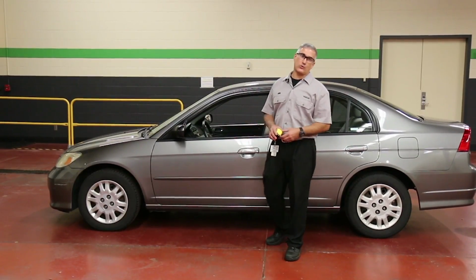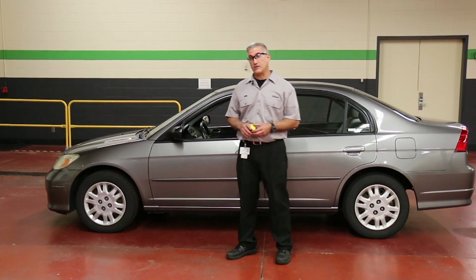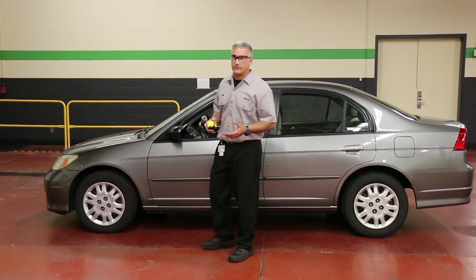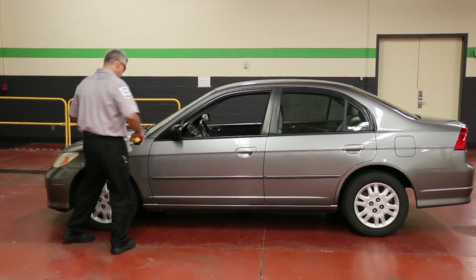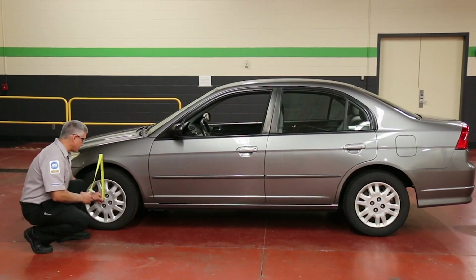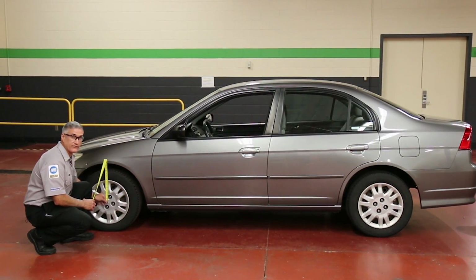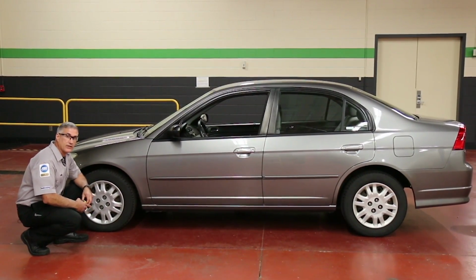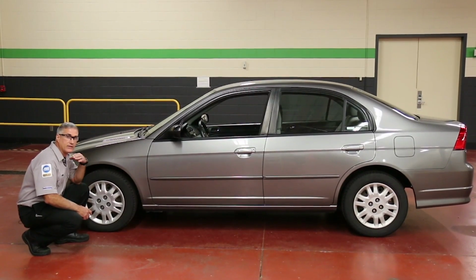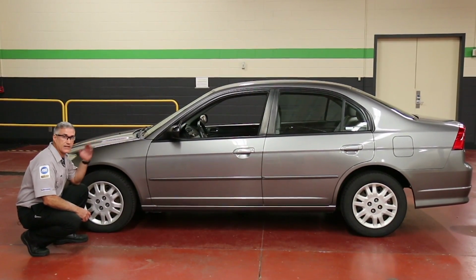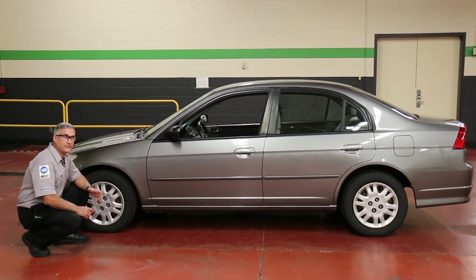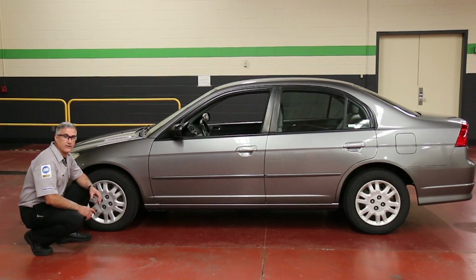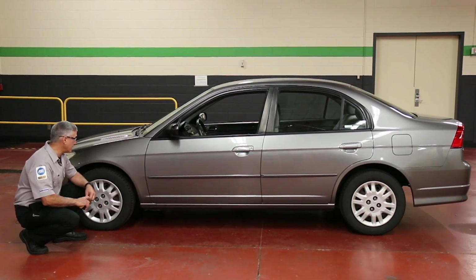Okay, so what do you do if there's no ride height specifications for a vehicle that you're inspecting? Well, although body designs vary from vehicle to vehicle, a good reference point would be to measure from the center of the wheel to the bottom of the fender lip opening all the way around the vehicle. On most passenger cars, that measurement should be within 1/2 of an inch of each other from side to side and front to rear. If it's an SUV or a truck, it's normally within 3/4 of an inch of each other front to rear and left to right.